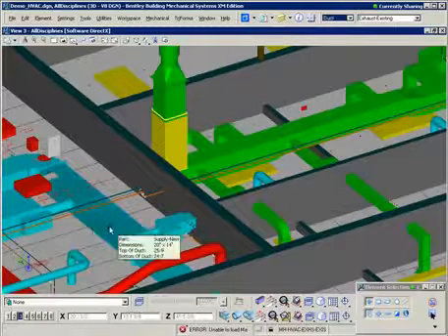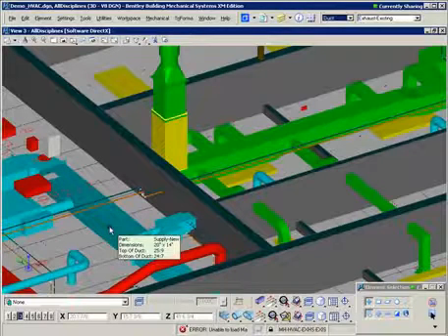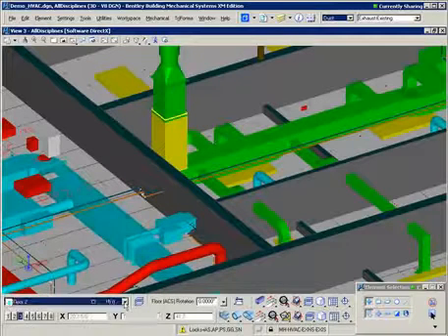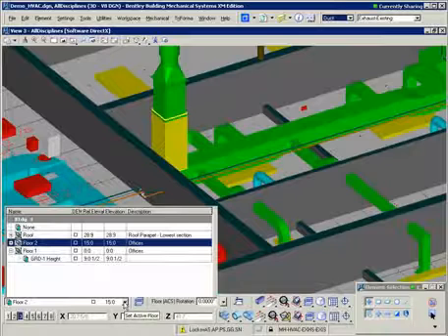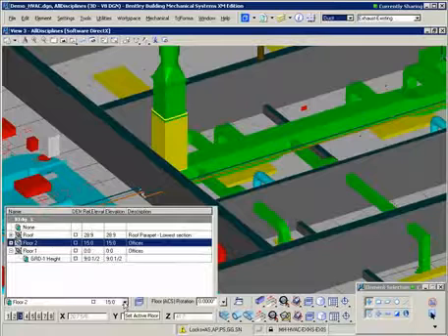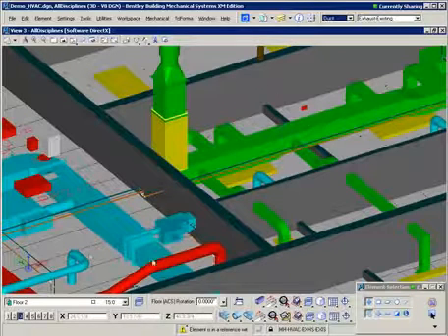And as soon as I do a flyover, then you see that the top of the duct and the bottom of the duct values have changed. So now you can really see that the elevation changed. That means that any ductwork, any pipework you set, you can check what the elevation is, referring to the floor you are actually in.